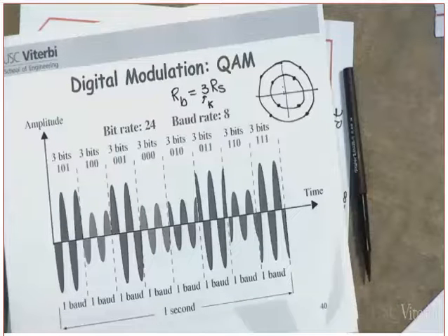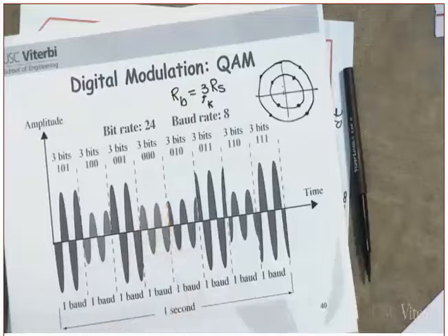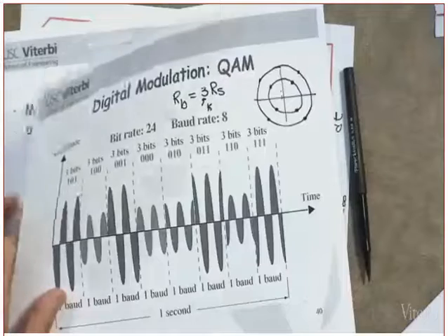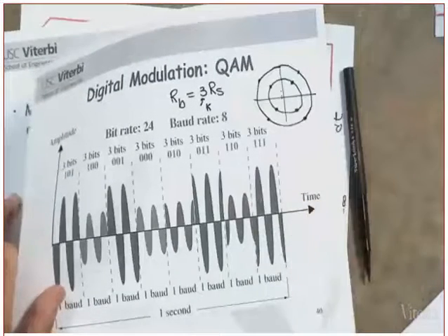If the power amplifier is non-linear, and this one has a variable envelope, you are going to get all the spectral side lobes that you have already filtered. They will show up again. It will tell you, hey, I came back. And with a sarcastic smile, they tell you, you cut me off, I came back again.